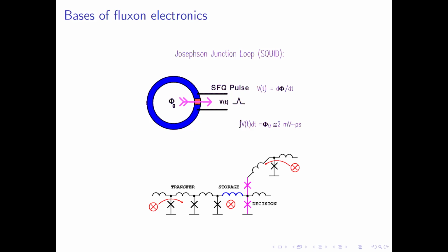It was developed by Japanese researchers, by Fujisawa, by Fujimaki and Yoshikawa, for example, and a bunch of other Japanese colleagues. And then came the invention of adiabatic quantum flux parametron logic, which is even more energy saving. This is 1 million times less, while rapid single quantum flux electronics is 10,000 times less than semiconductor CMOS. So this basically constitutes classical operations on superconducting circuits.